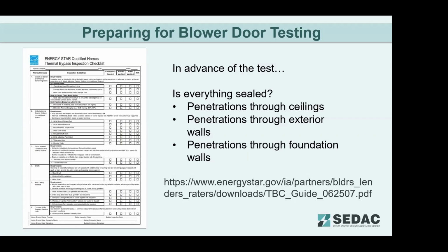Energy Star has a very nice reference guide called the Energy Star Qualified Homes Thermal Bypass Inspection Checklist. If you follow that link, or just do a quick Google search for thermal bypass inspection checklist, it gives you a very nice checklist of all the things to look for, from chimneys to recessed lights to plumbing stacks to duct penetrations and whatnot.